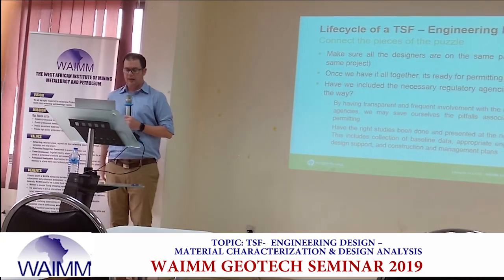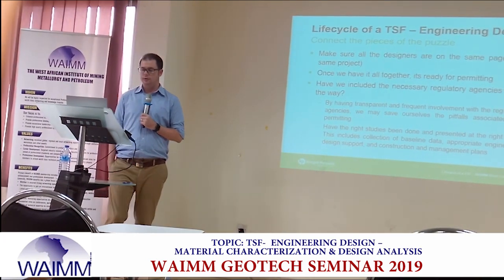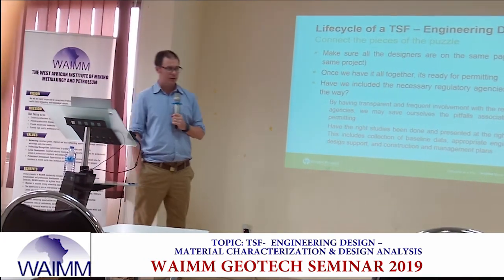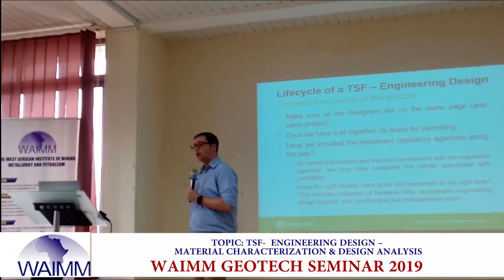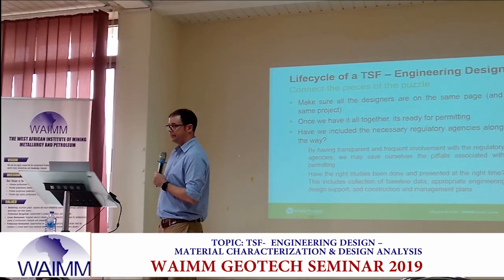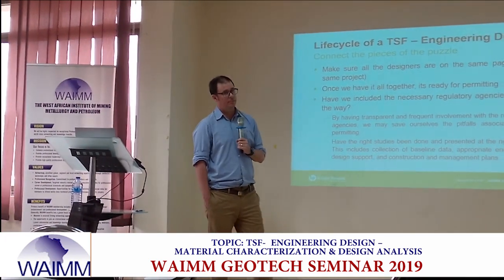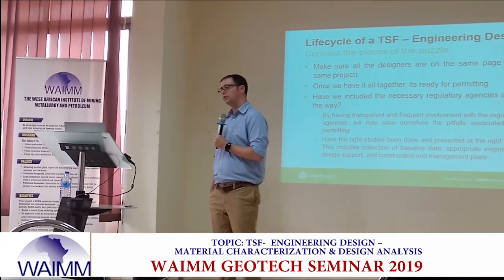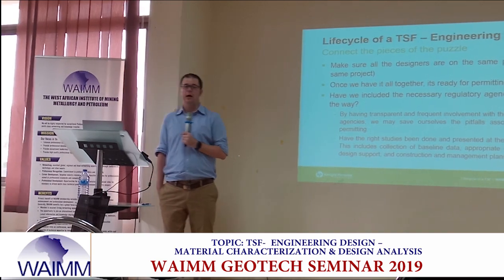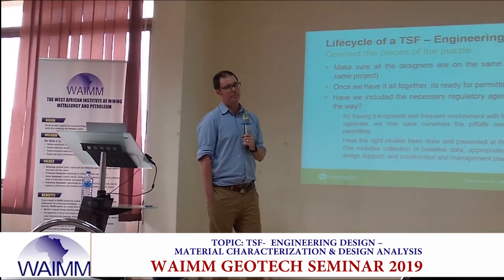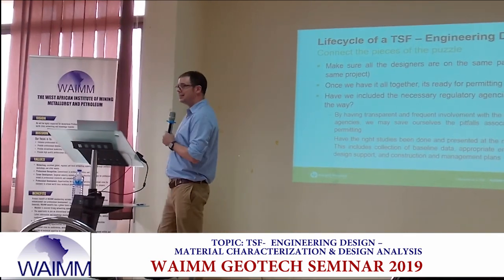Then, now that we've connected all the pieces of the puzzle, we need to make sure the designs, the designers, the projects are all on the same page, okay? And by this I also mean we're not only building a dam, we have to operate it, okay? Have the designers of the pipe and pump system been on the same wavelength with the guys designing the tailings facility? If the pumps and pipes designers assume a 20-meter tall dam, and I want to build a 50-meter tall dam, they won't be able to get the tailings into the basin.